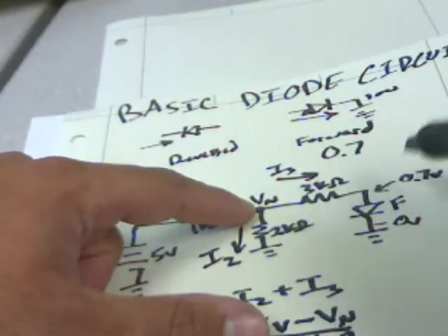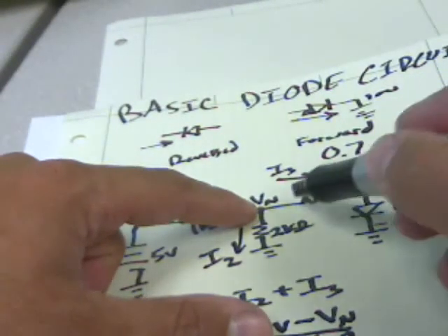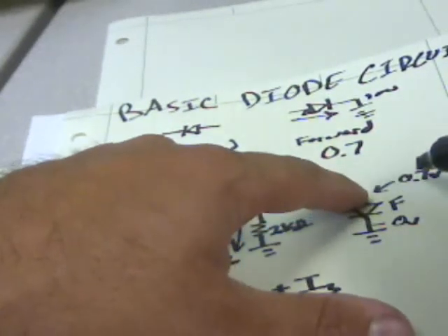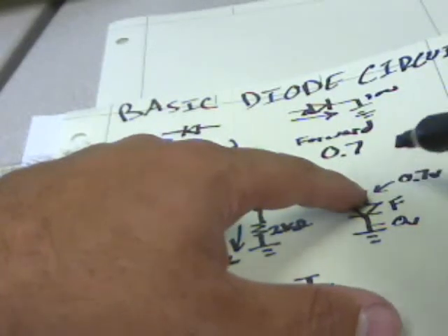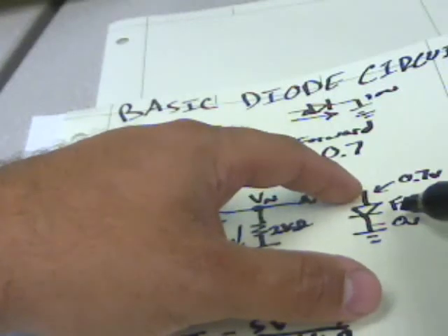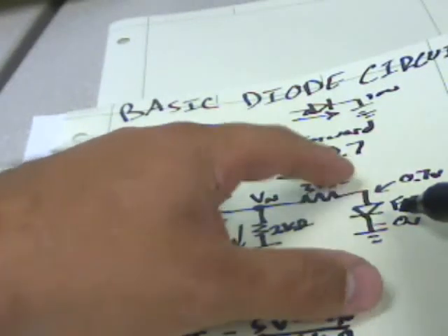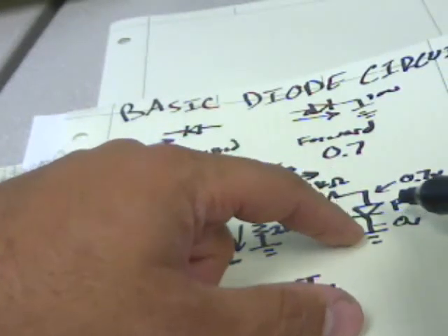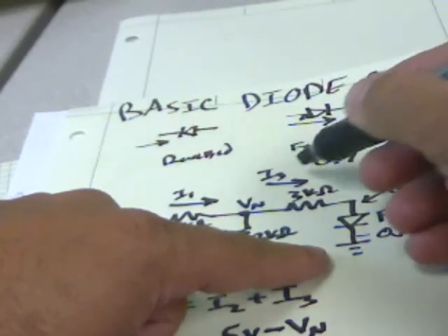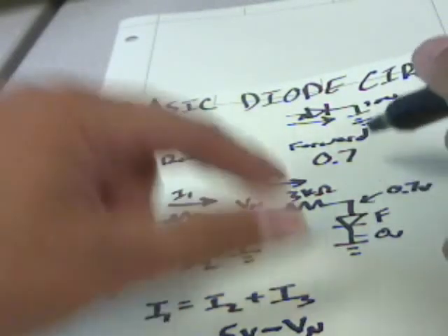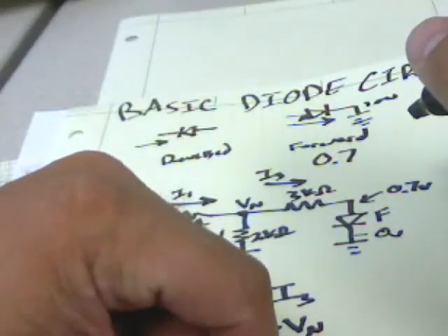So Vn is going to be 3.33 volts if this is reverse biased. But because there's no current flow here, that means there's no voltage drop here, so the voltage here is no longer 0.7, it's 3.33 volts. Well, if you have 3.33 volts here and 0 volts here, that means you have a larger than 0.7 volt drop across that diode, which is not possible. The current has to be flowing the other direction, so that obviously means that we've done something wrong.